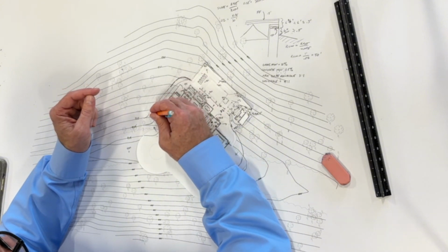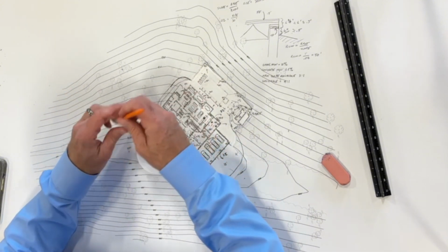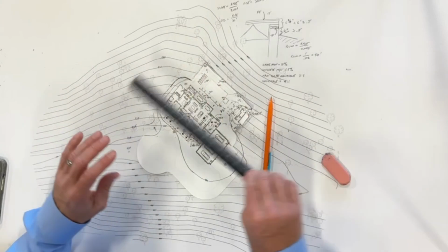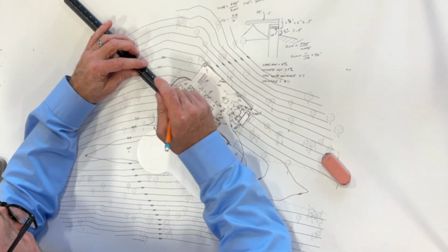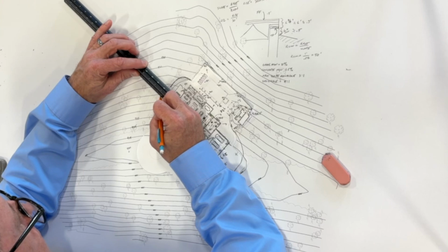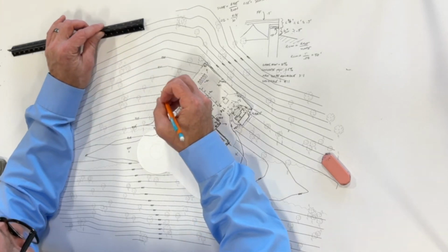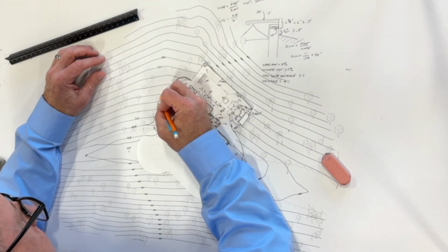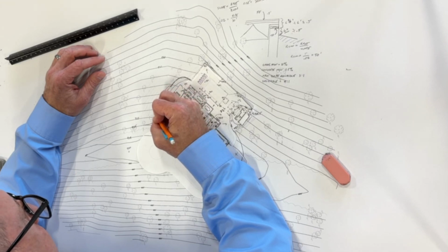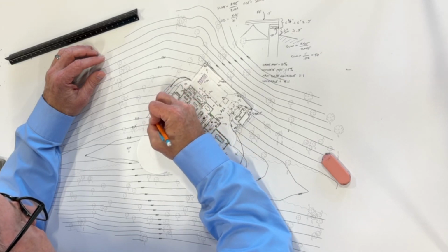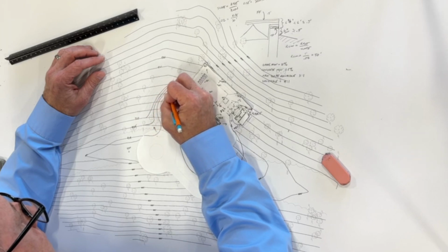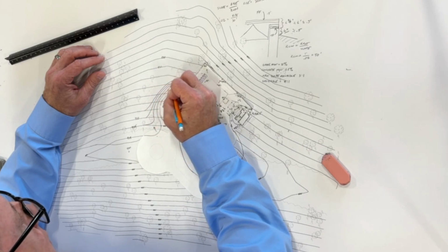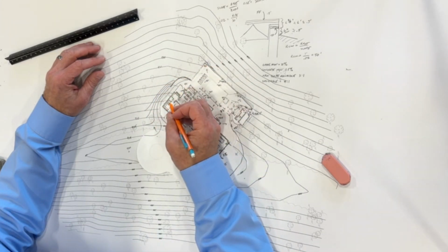And then what we're going to do is have these other contours come, and because we know it's not going to work real well, we're going to go to a 3-to-1 slope, which is mowable but not awesome, just because we're fighting the slope here. So it's about that far. So that much distance right there. So we're going to have that hook to catch that wall. And then that's going to be the 938, 937. It's going to be right there. Going to dive in. 936. So now I'm putting these lines much closer together. So that represents, we know that that's going to be steeper.